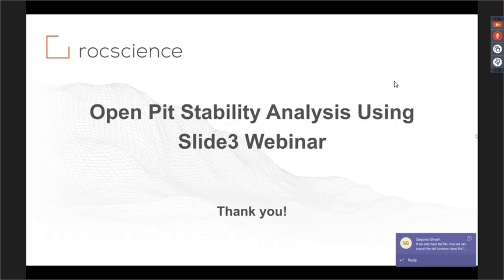If we only have DXF files, how can we import the DXF file and set up the material model using only Slide3? If you've got the DXF files from your geological modeling software or your mine planning software, you can import these directly using import geometry. There is a webinar, if I can skip back.